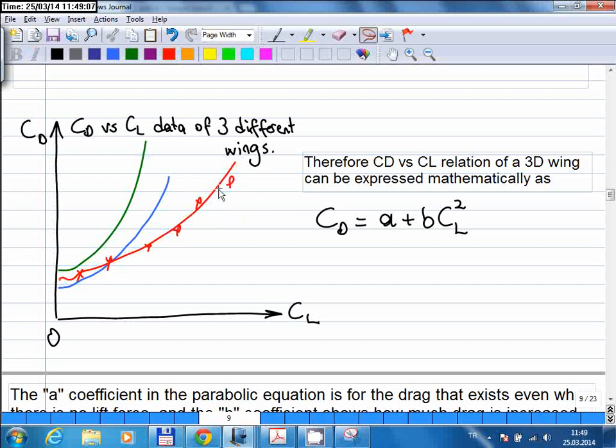Does everybody agree with that? The important thing is, as I said before, the ratio of the two. You want large lift force, but you want small drag force. And if you compare these three designs, then this red one really gives you the best performance in that sense. Because if this is, for example, the lift coefficient you need, then the red curve gives you the lowest drag coefficient for the same amount of lift coefficient.